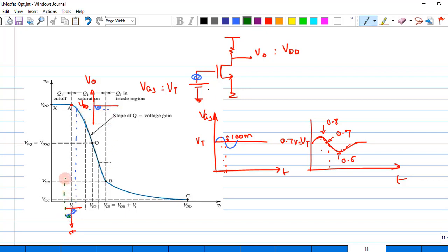So this spot would then intersect the same value of VDD. Now, how would the graph then be built for the positive cycle of my output? Should I draw something like this? Can I draw like that? What is this value that I'm hitting? Same as VDD. So you cannot go beyond the value of VDD. You have to stick with this value of VDD, so your waveform is getting clipped off. Obviously this is not a good spot to have our Q point.